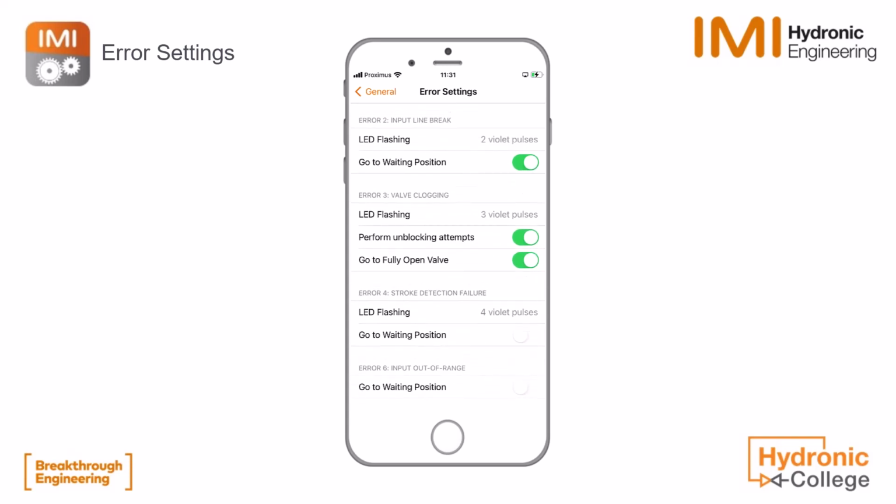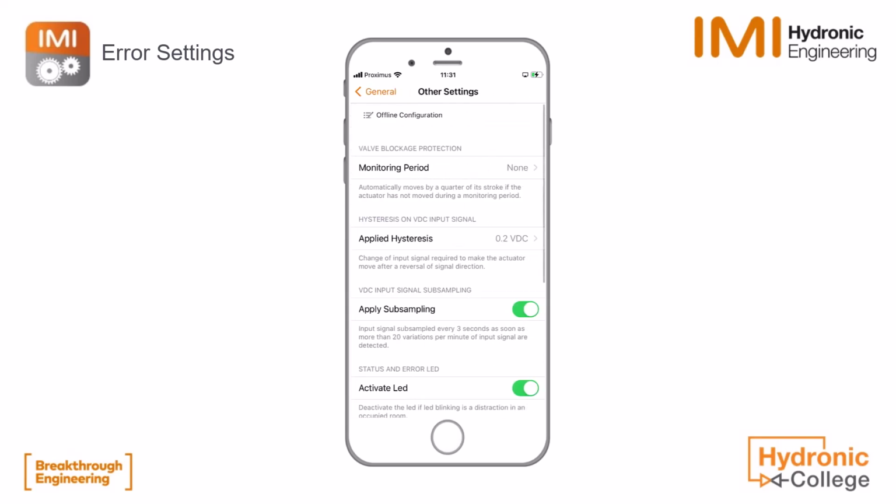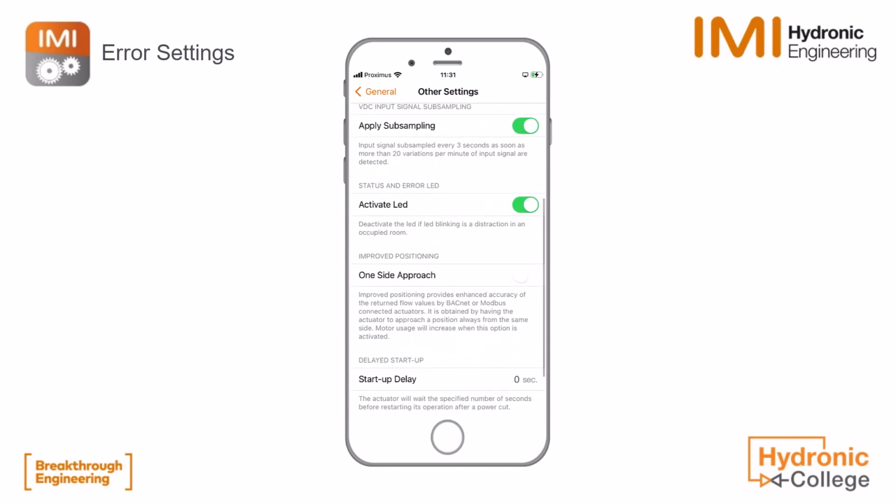And then we have the stroke detection failure. Also there we can go to the waiting position if needed, if the installer wants it like this. And then finally we have the input out of range. Then we will ask to go to the waiting position also or not, depending on the installation, depending on the specific application.